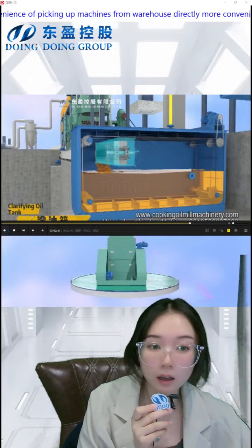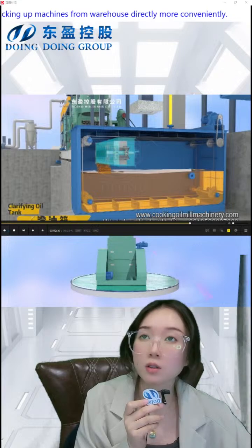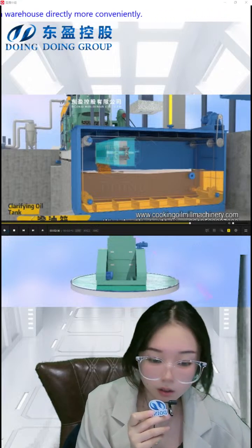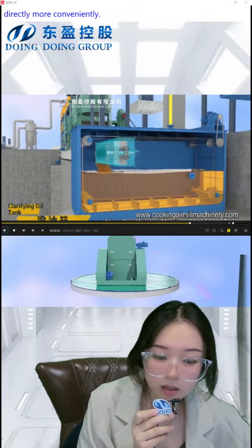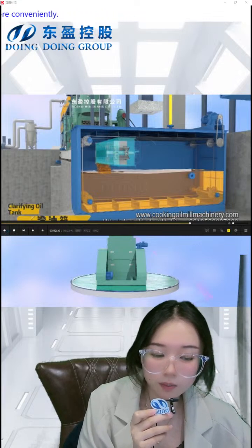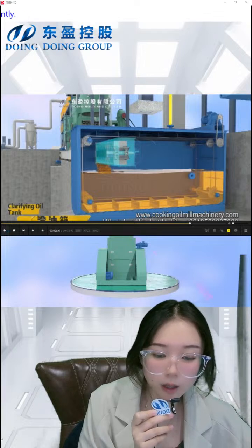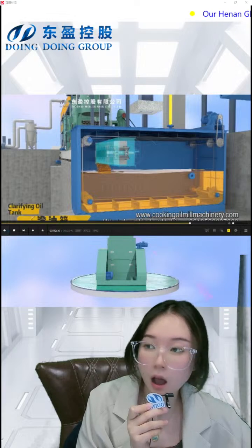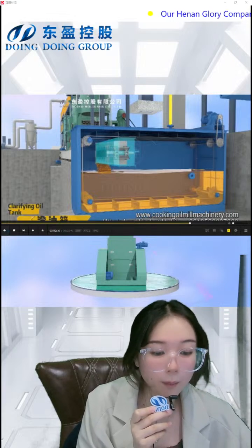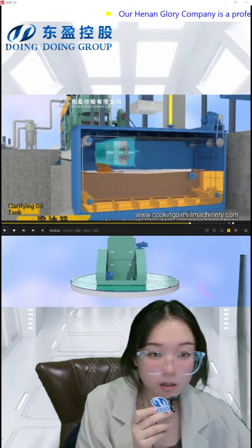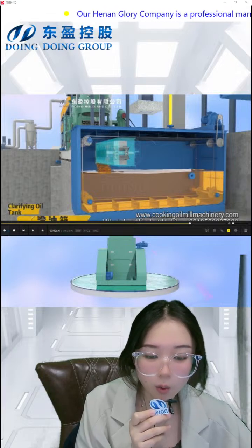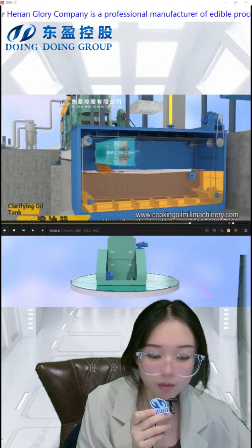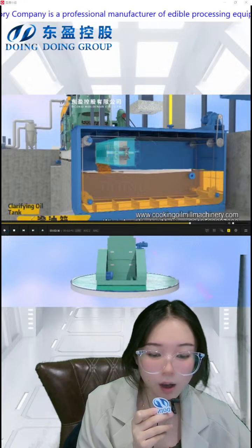The clean oil tank is the first step in our filter section, which can serve as temporary storage, control the production rate, and improve production efficiency. On the other hand, by standing still, the oil residue will settle to the bottom of the oil tank due to gravity, making the crude oil cleaner.